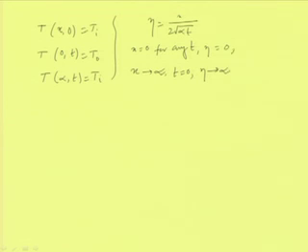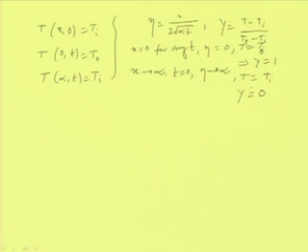So, when eta is equal to 0, T equals T I... and here we know that Y is equal to T minus T I by T naught minus T I. So, for any t, for x equal to 0, T is equal to T O, this implies that Y equals 1. And for x tends to infinity or t equals to 0, here T is equal to T I, this implies Y is equal to 0. So, this is the reduced form of the boundary conditions: eta is equal to 0, Y equal to 1; eta tends to infinity, Y equals to 0.